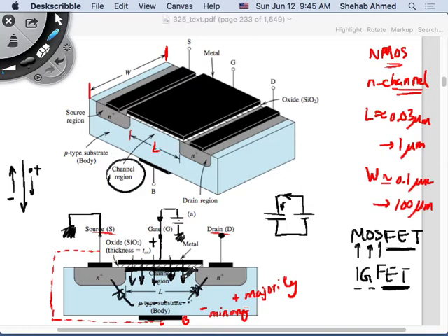So I still have zero gate current coming in, even though I still have this voltage that has this electric field created due to it, which pushed the holes down, pushed the electrons up, and created this N channel here. Okay. Now that I have this N channel, what can I do? So far, I've only been talking about the gate to source voltage, and I left this, let's say, initially at ground. Okay. So now with this left at ground, what I said is okay.